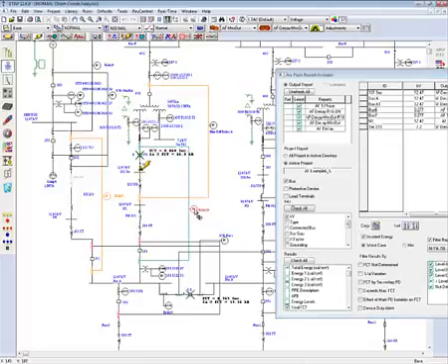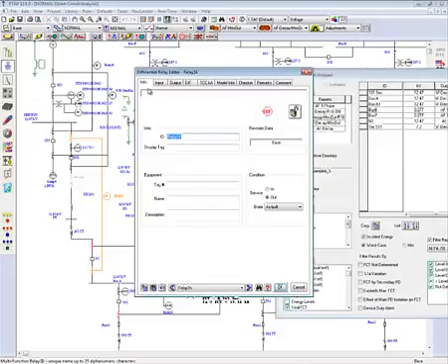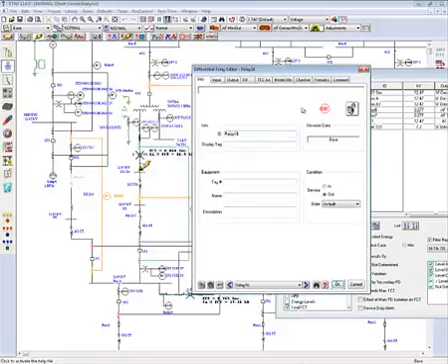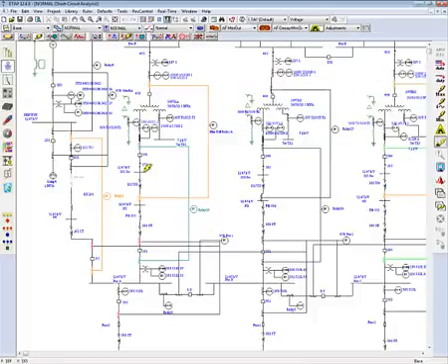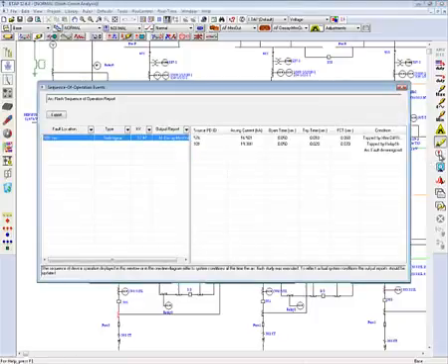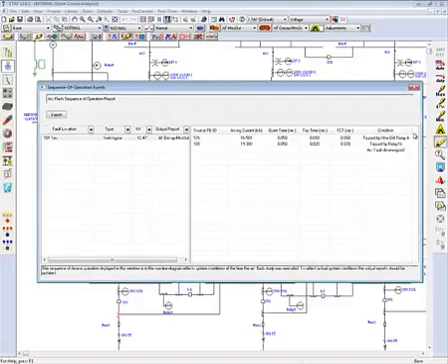So I'm going to double click it, and I notice right away in my info page that my condition is set to out of service. So if I were to put this back into service, I should expect my differential zone operating. And as you can see, the differential relay 16 zone is now de-energizing this fault well below 100 milliseconds, and you can see that change in incident energy. And of course, by launching the Arc Flash viewer, you can also see this.